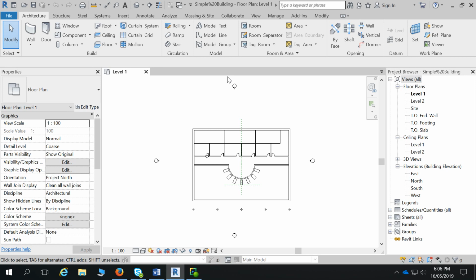We'll probably get through that in about the next half hour, and then we're going to get into loading a DWG file into a project and start drawing a project that way. Then hopefully tonight we'll get to putting in doors and windows, and next week we'll put a floor and a roof on it and a ceiling. So you guys can get used to loading in families and that sort of stuff.